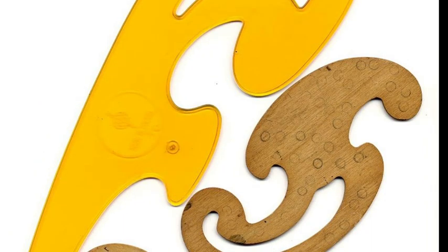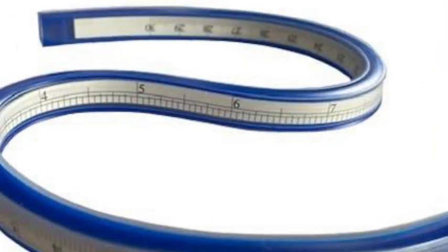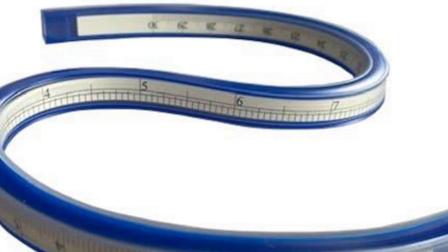Also, for drawing curves other than circles, you have your flexible curve. Now this one, I actually prefer it to the French curve. It's just that the French curve has some, let me not say cheat methods, but some easy methods. For example, those of you that are very observant, if you have seen a French curve before, some French curves have some dimensions on them, like you can see 40, 50, 30. That means 40 millimeter diameter, 30 millimeter. I'm going to be teaching you how to use them. But this is way easier, especially when you start drawing special curves. Yes, you will need this flexible curve.